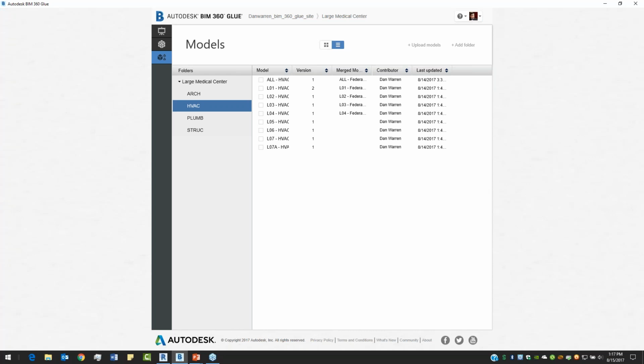And we're breaking a very large building into smaller pieces. The example building I'm using in this webinar is 6 stories, so it's a pretty sizable building and there's a lot of data to manage. If you're doing a smaller building, that's one of those considerations as an admin you have to work into your plan. Are we going to be able to manage this as one big federated model, or are we going to be managing this in smaller chunks? Typically, you'll end up breaking it out in chunks.